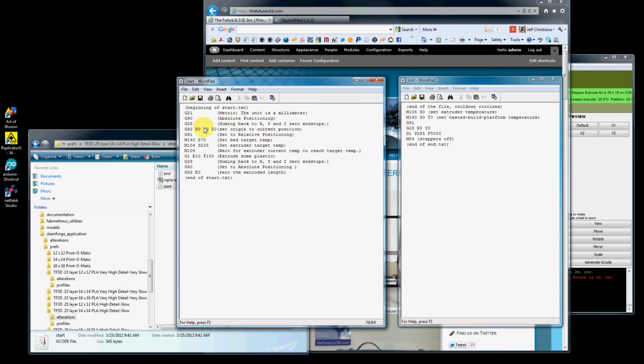If you want to do different things during startup, I have found this to work and prime the head and get it going. If you wanted to prime some more, you want to add to your extruder time here and change that to 20 seconds. The more you extrude, the more you just want it to extrude enough to fill the chamber when it's sitting there heating up and some is oozing out. So you just want the right amount. And you can even change your feed rate. I mean, you can go up to 600 on this, but 100 is what I would recommend.